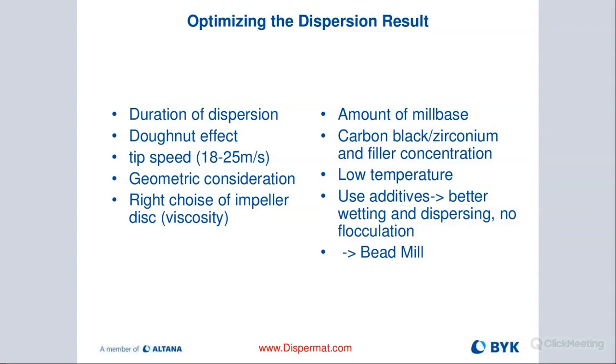The filler concentration of our raw materials that we're putting in, we're trying to keep the temperature as low as possible. Better for the product usually, and for that we control the temperature with the chiller, with the containers that are jacketed, and also the PT100 probe that measures in real time, and then you get the readout on the control panel of the Dispermet, where you can then program these cutoff values we talked about earlier, and also warnings.